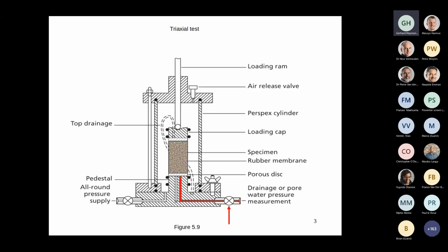That can only happen if the air entry value of your clay is sufficiently high that you don't get air entry. So for a sand or a silt, it won't be possible because it only takes a few kPa for air entry in a sand or a silt. For a clay, it is possible, but it needs to be fully saturated even before you start.